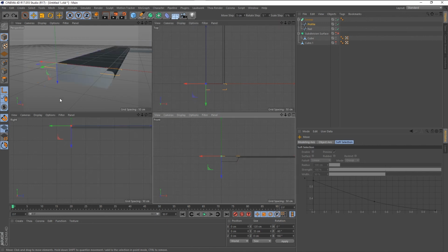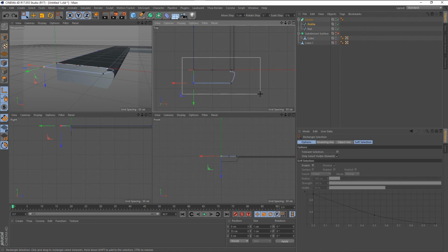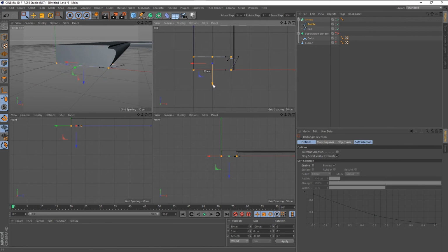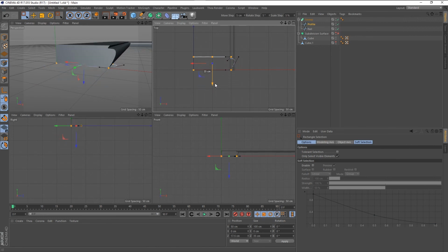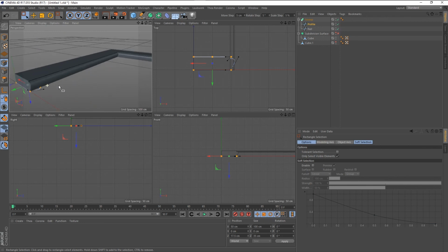So what I would do is go into point mode and look in plan view here. Hit 0 for your window select. Make sure you turn off the axis. We don't want to modify the axis anymore. What we want to do is move this up. I'm going to move it up to there. There we go. See how that worked? And now it's oriented correctly. It's following my rail. And it is working as the profile I intended it to be.